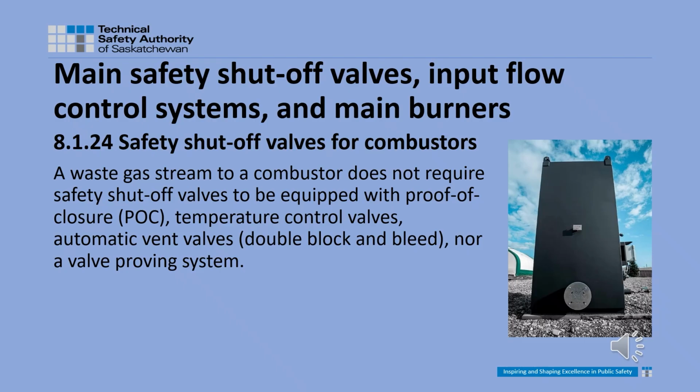Saskatchewan Codes of Practice 8.1.24 Safety shutoff valves for combustors. This gives an exemption. Safety shutoff valves with proof of closure, temperature control valves, automatic vent valves, valve proving systems, or VPS are not required on the waste gas stream to a combustor.